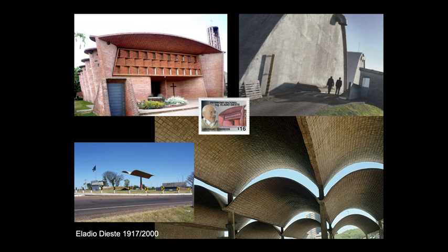He's covering it with a steel network and adding the concrete on top, and then he finished it with a skin to save it against the rain and other inputs, so to speak, from the surroundings. So the sun in South America is also very important. If the concrete dries too fast, then it also can be problematic.